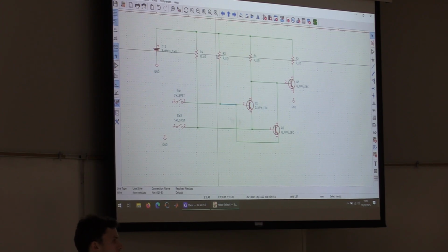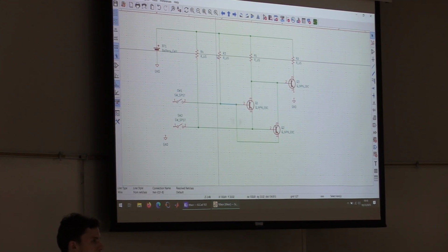And if you want to be able to connect nets across different sheets in your hierarchical design, you would usually use the name of the net to correlate them. Meaning if you have two sheets and you have various 12-volt sources, say from a 12-volt battery and then a 12-volt power supply, you don't want them to be electrically connected, and if you name them both the same thing, the software will think they're electrically connected. So make sure to give unique names for each node or net.